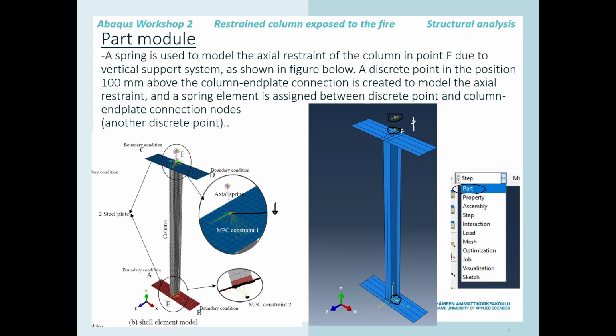So we will now have this type of partitions, which is shown over here. The idea is to have this partition from the middle one time, in both directions, x and y, and then some extra partitions so that the I-beam cross section will match directly to the plate. So that's why we need to do the partitions.